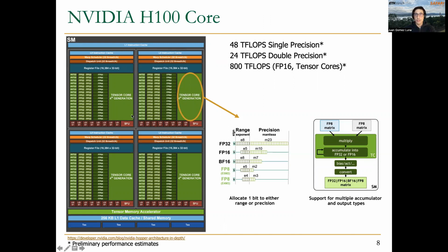And in some sense, this reminds a lot of vector processors and array processors that we explained in the previous lecture. As we can see here, there are units for 32-bit integer computation, 32-bit floating point or 64-bit floating point operation. There are also specialized units for load and store access memory, and there are these specialized tensor cores for neural networks and machine learning.